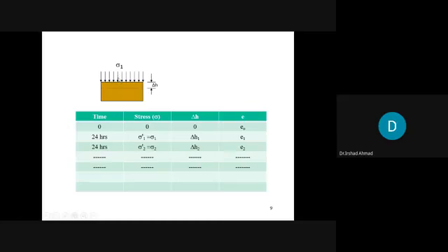The effect of this stress would be to generate excess pore water pressure into the soil specimen, right? This excess pore water pressure, because there are drainage boundaries available on top and bottom of the soil specimen, drainage would take place in the vertical direction, both above and below.